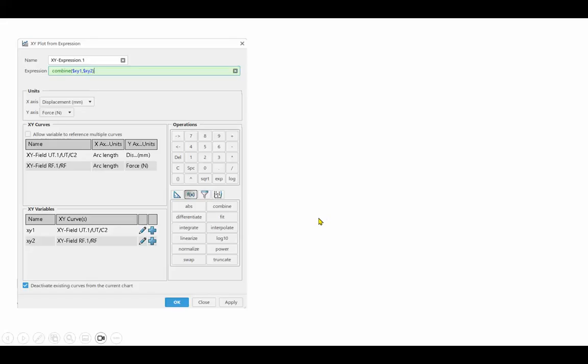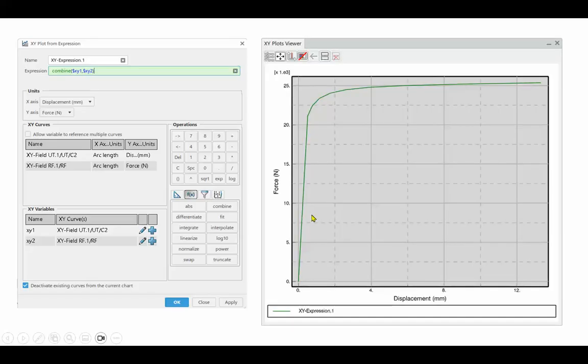And those are with respect to the arc length. So we're going to change them with respect to each other, force versus displacement. And this is what you get. Notice that here, in this static Riks step, we did not tell the software what the linear buckling load was, but it's going to pop up right there. And incidentally, this goes past the 10 millimeter that is specified because probably the last step was very large. That's why it chose 12 millimeter.